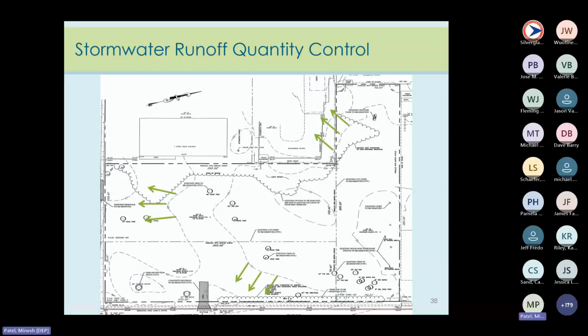So it was determined that the drainage areas were not delineated correctly. Whether or not that was due to an incorrect evaluation of the topography, that's unknown. But this does show why it's important to properly evaluate the topography and delineate the drainage areas.